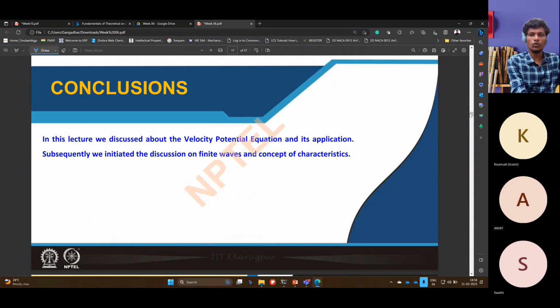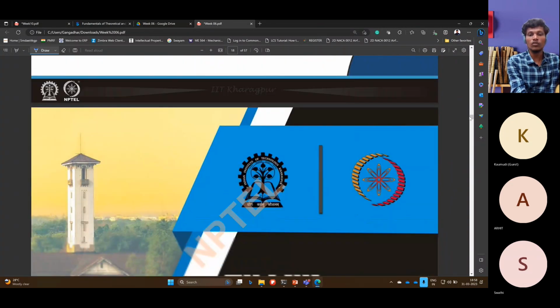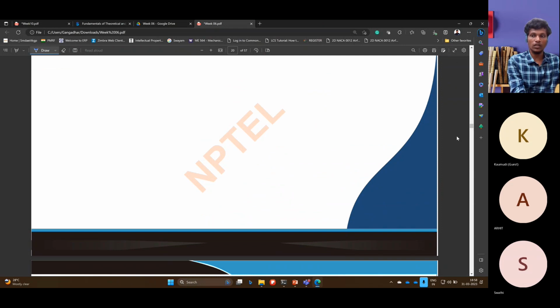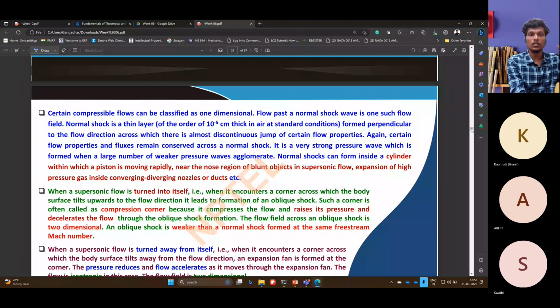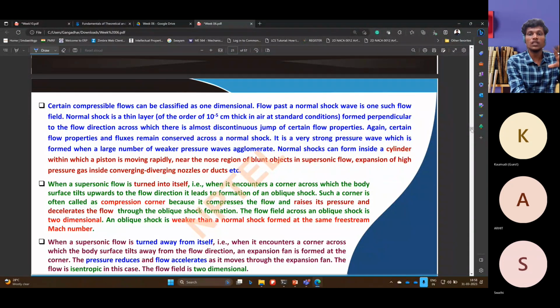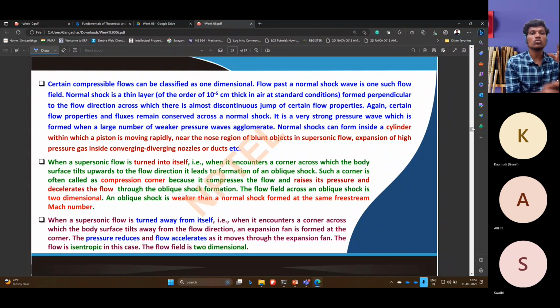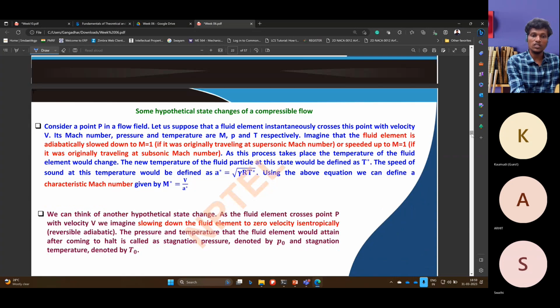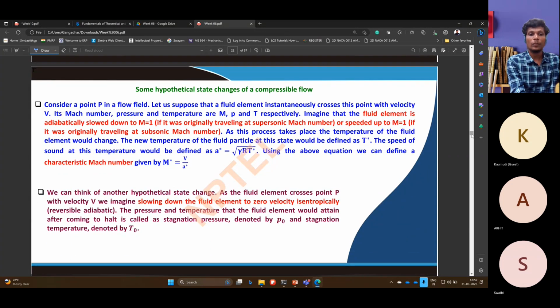So except for the shock wave formulations, you can relate any governing equations from subsonic to supersonic, and those are still valid up to a certain level. We also have to see the assumptions given for deriving any formulation in this chapter, because many formulations start with the governing equations of continuity, momentum, and energy. If we are deriving for the shock wave characteristics, we will start basically with the momentum and energy equations, which involve only one-dimensional formulations.